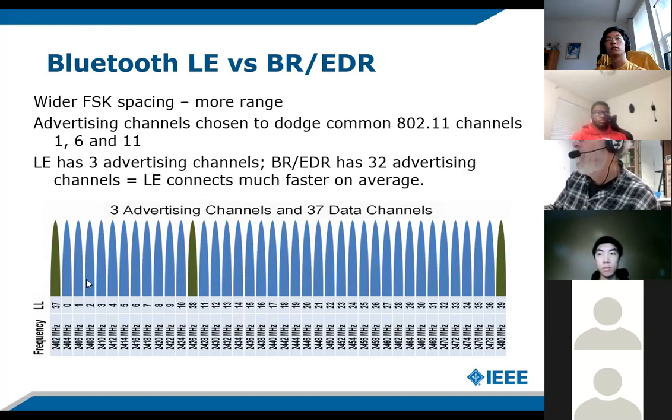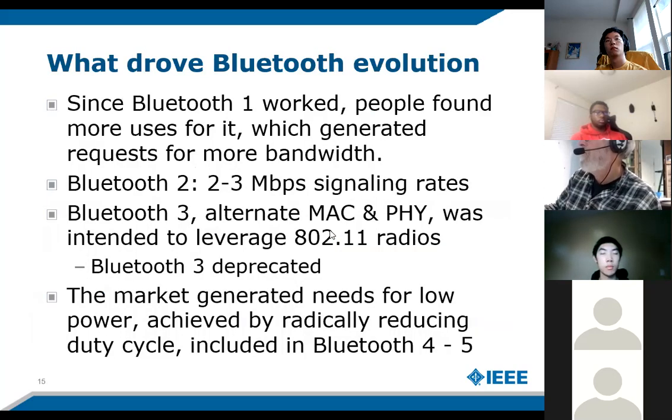They'll start using the bands that aren't busy. If you happen to be in a house with two non-overlapping Wi-Fi bands, maybe one of them eats up this and one of them eats up this, so the Bluetooth devices will jump around over here because they'll discover that they aren't blocked, whereas they'll discover that these are temporarily blocked. I'm trying to explain what adaptive frequency hopping means.